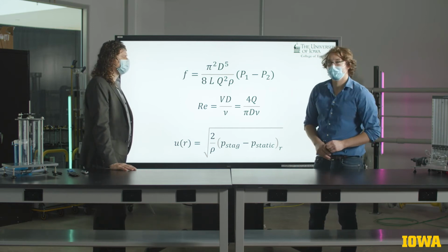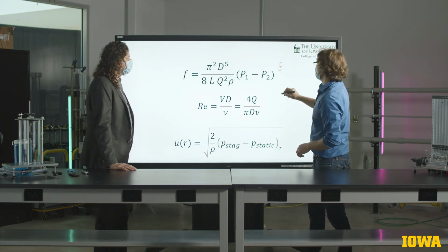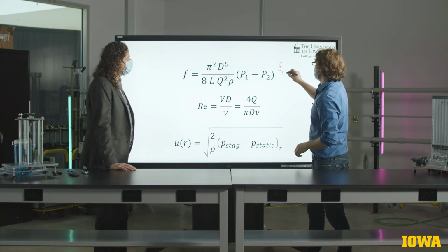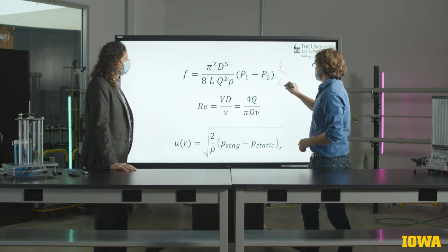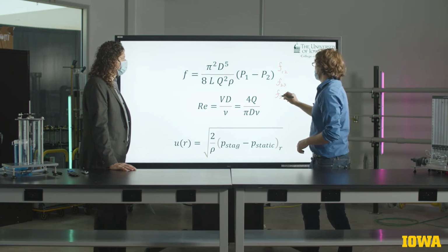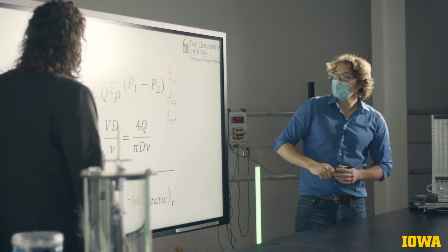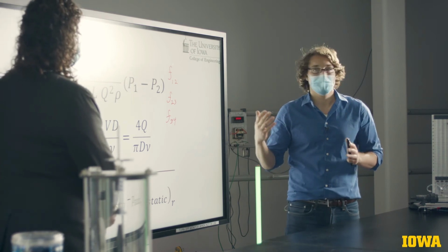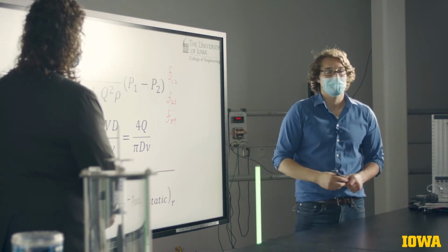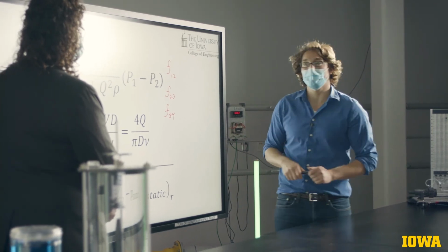One of your options for the friction factor is to, for example, calculate the friction factor between taps 1 and 2, as written here, between taps 2 and 3, and between taps 3 and 4. And please remember that taps 3 and 4 were each measured 10 times, meaning we'll have 10 independent estimates of the friction factor between 3 and 4, which we'll talk a little bit more about in a moment.